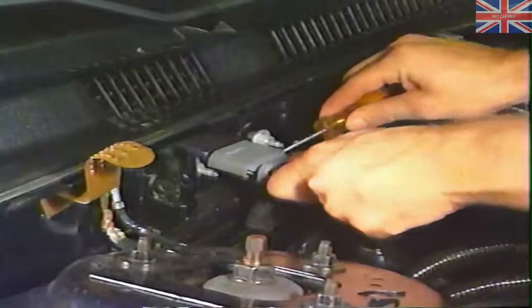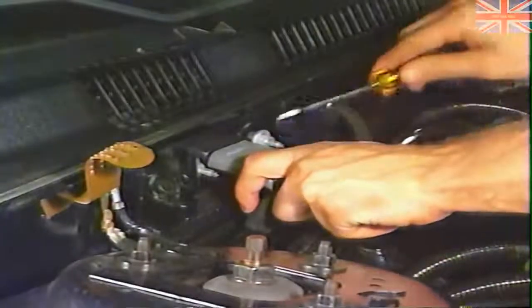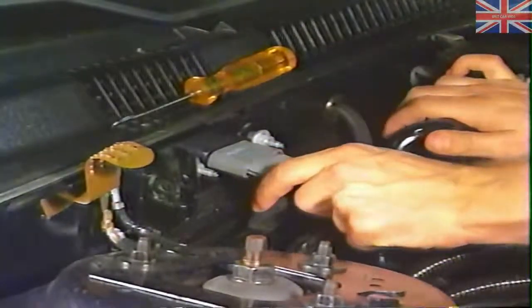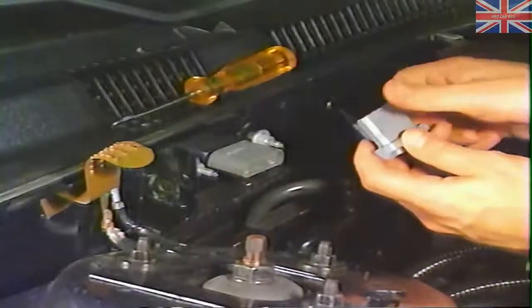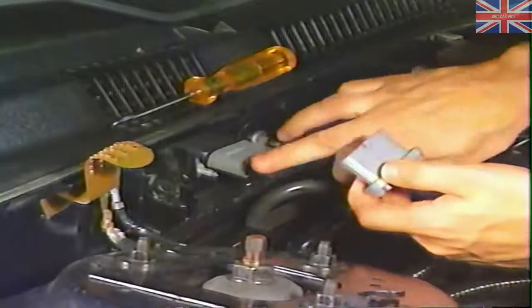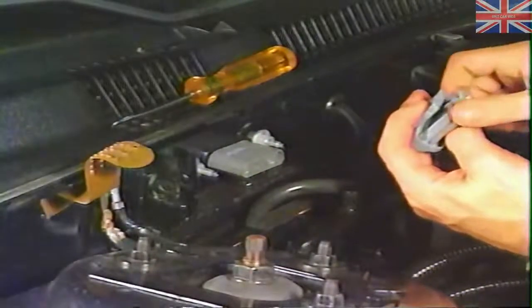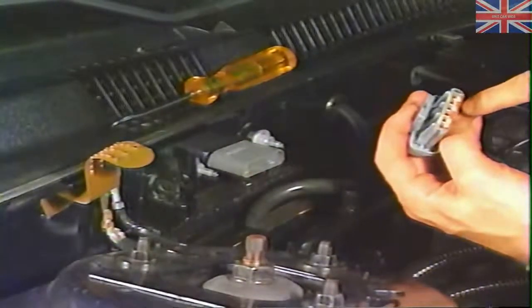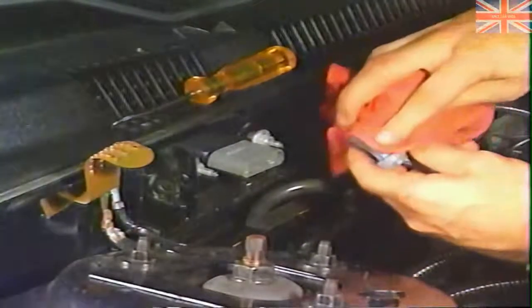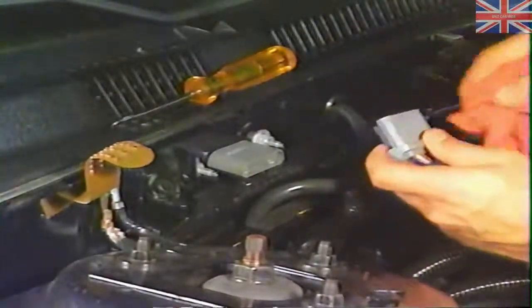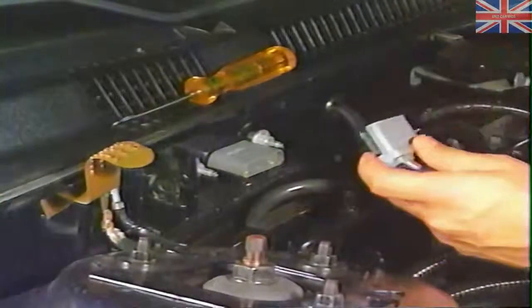There is the problem. Someone has left the weather pack seal off the module assembly. It appears that a replacement unit has been installed in the past, and with the weather pack seal left off, moisture has caused corrosion on the pin connectors. It will be necessary to thoroughly clean and dry out the TFI module and the harness assembly. Install a new weather pack seal.